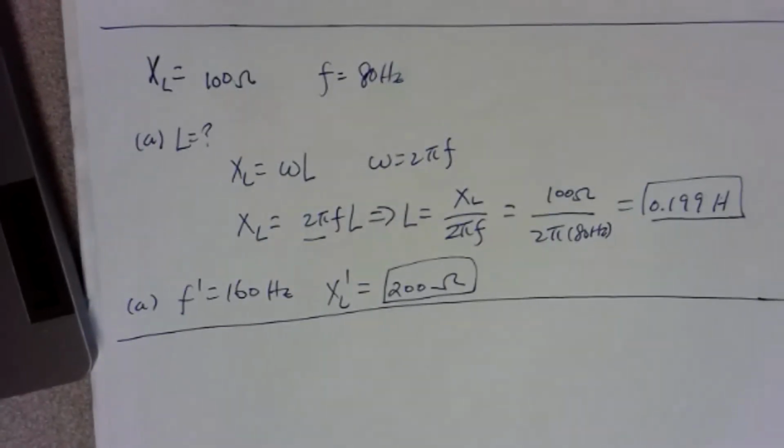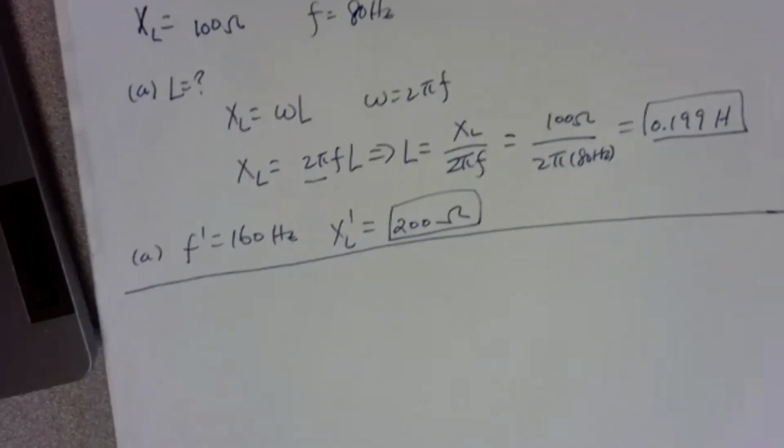It says: calculate or predict. A 22.0 microfarad capacitor is connected to an AC generator with an RMS voltage of 118 volts and a frequency of 60 hertz. What's the RMS current in the circuit? If you wish to increase the RMS current, should you add a secondary capacitor in series or in parallel? Find the value of capacitance that should be added to increase the RMS current to 1.50 amps. Okay, so let's start with writing out the knowns.